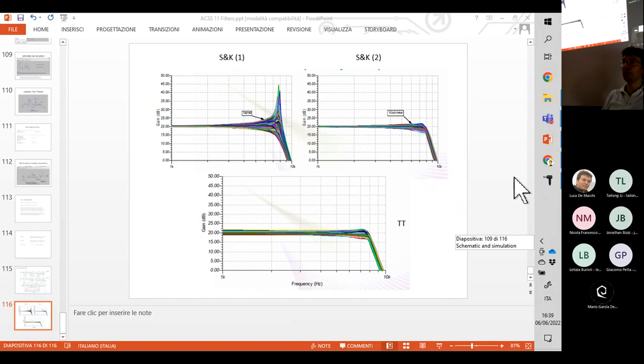Other mechanisms are based on ultrasound monitoring. In ultrasound monitoring, we actuate an elastic wave within a medium, and we receive a possible reflection or anomalous echoes to infer again the integrity of the structure.